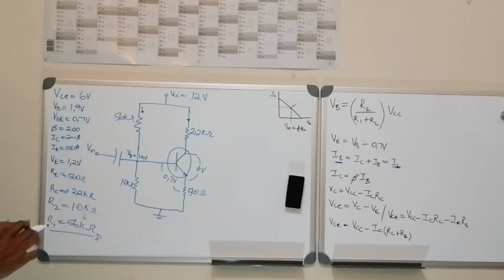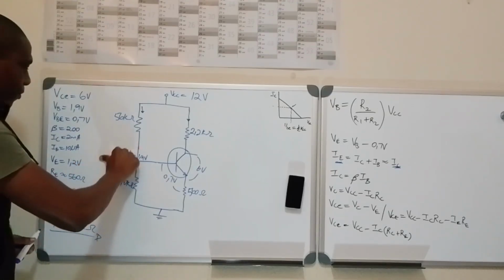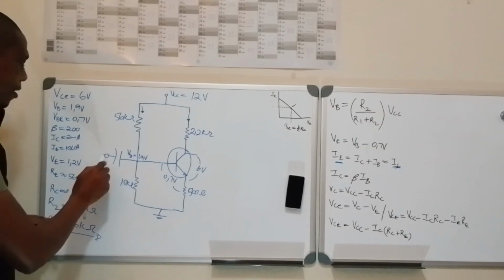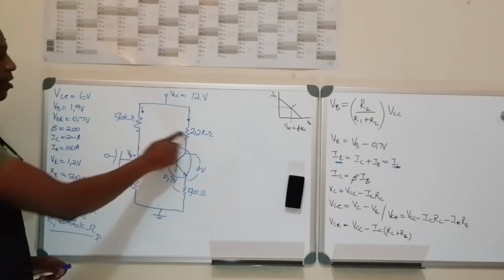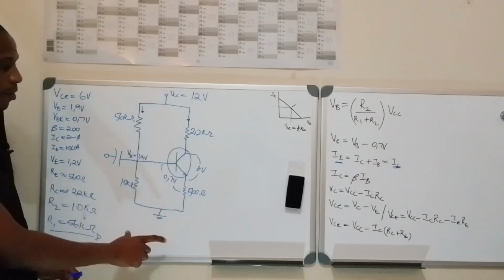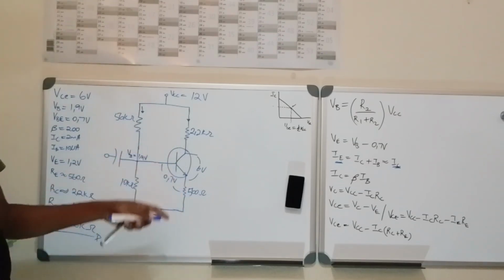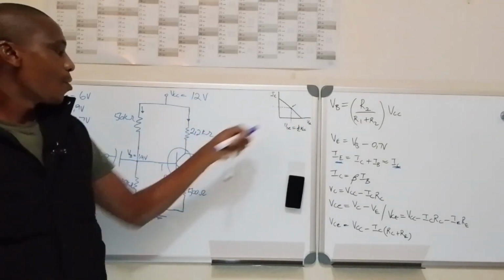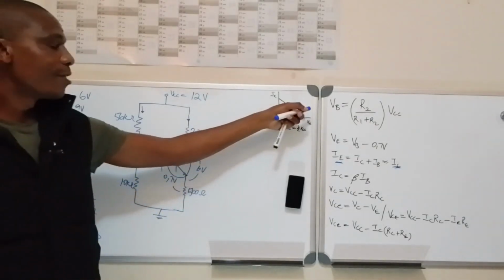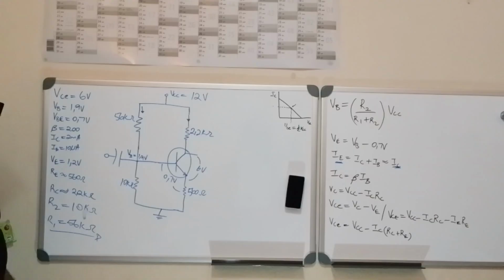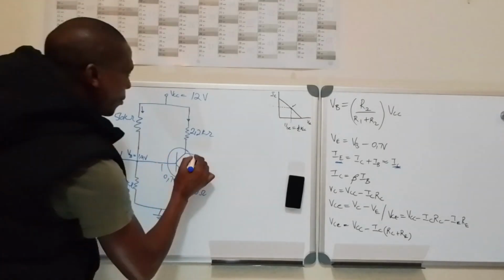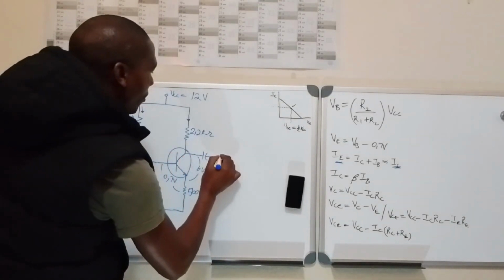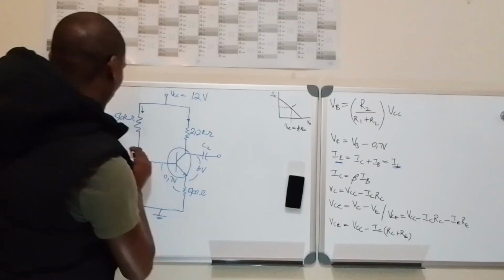So if we can get this type of transistor and put these resistors like this, connect it like this on a breadboard, with resistors of these values, we can almost operate this transistor in this active region. You see how we go about doing this in real life. Now when we do this practical, we'll also learn how to calculate the value of these capacitors.